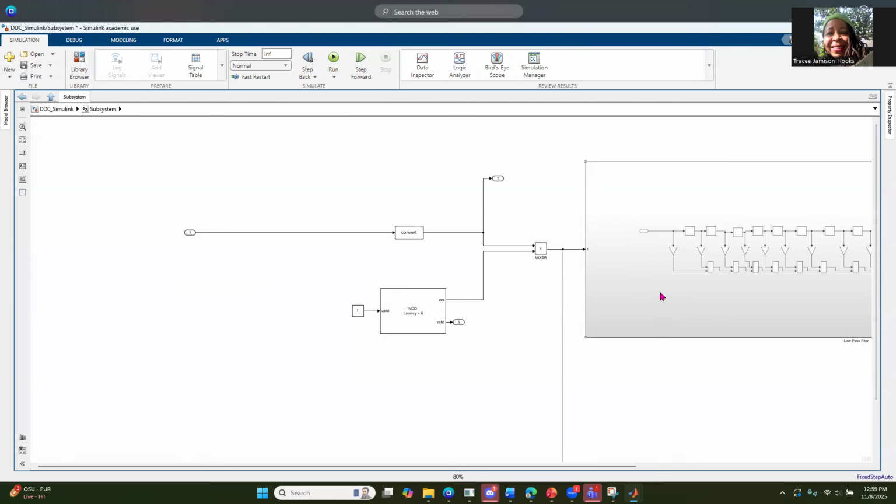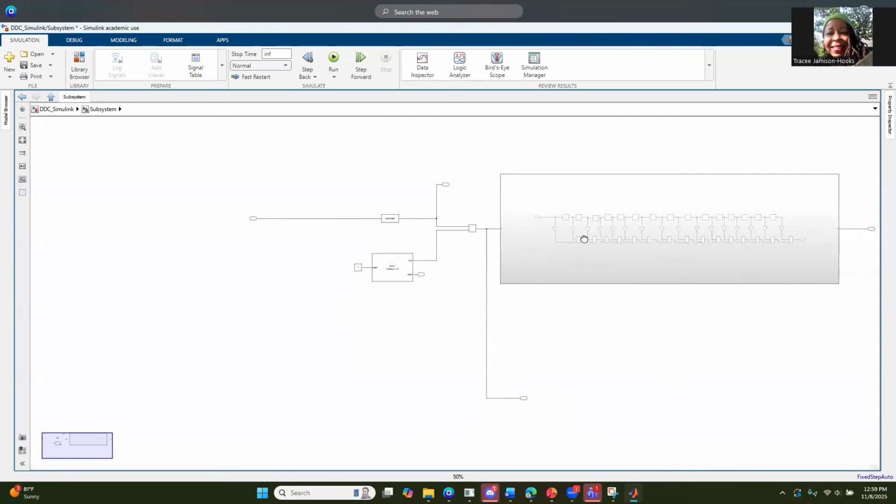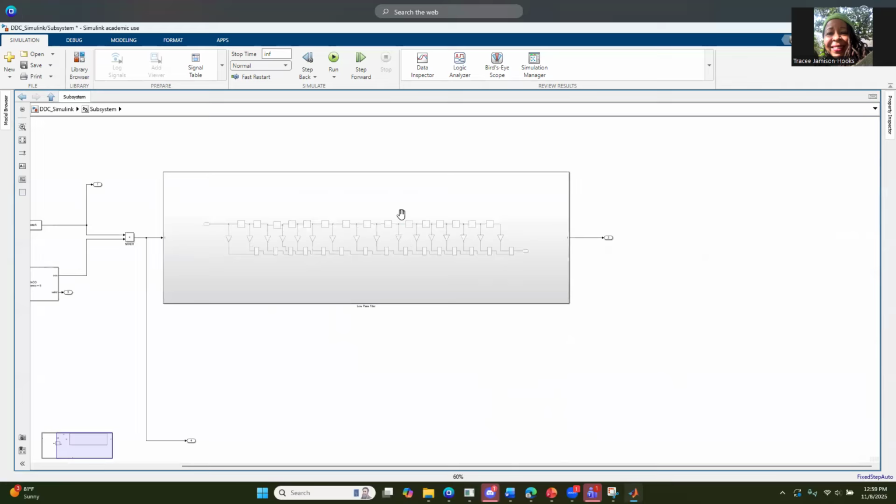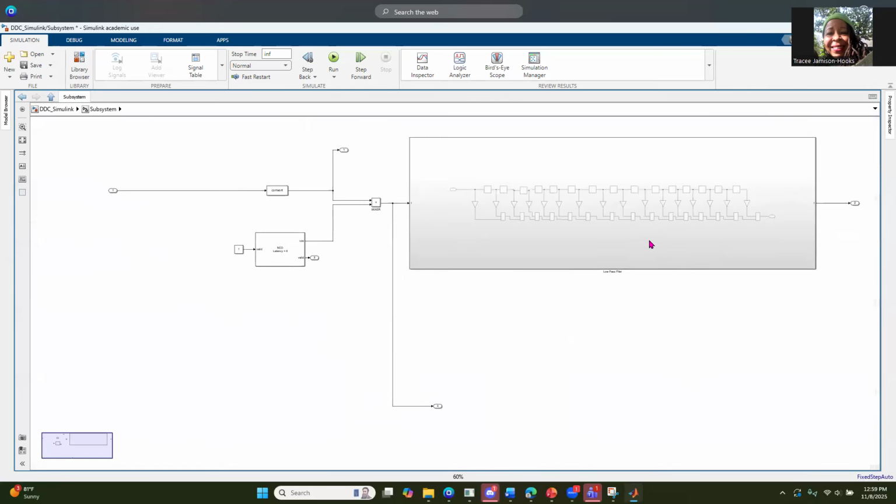And so once you have determined that a design would meet the requirements and timing and resources for an FPGA, then you can carefully go and code the design in space qualified hardware description language. And for that, you would need to understand how hardware description language works.